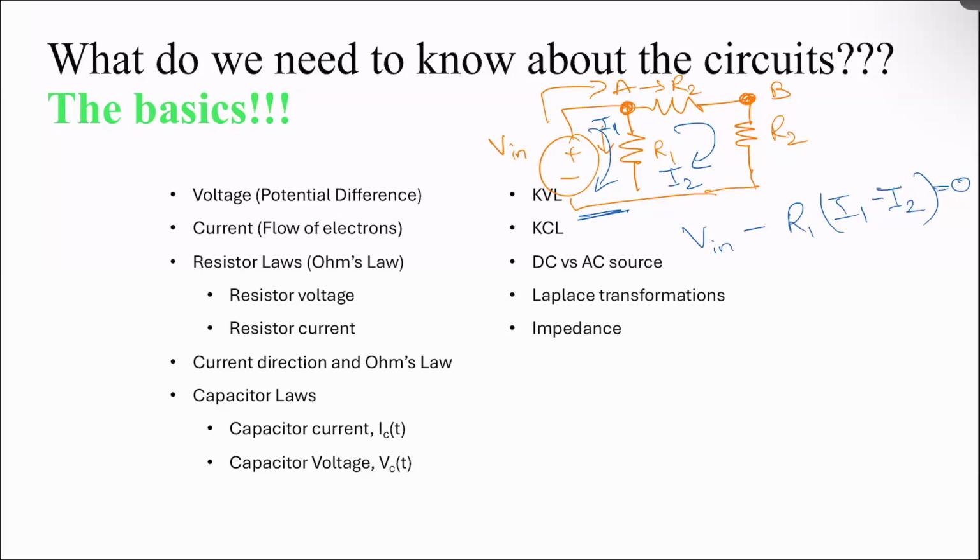Okay, now can somebody else tell me what the second equation would be for KVL? I actually have a quick question. I would have assumed that Vn would be negative because the arrow is going into the negative side of the voltage source. So it doesn't matter which one we do, negative or positive, as long as one's either or. You mean the current is going this way, but it's coming out of the positive end, right? Oh, so it's by where it comes out of, not where it goes in.